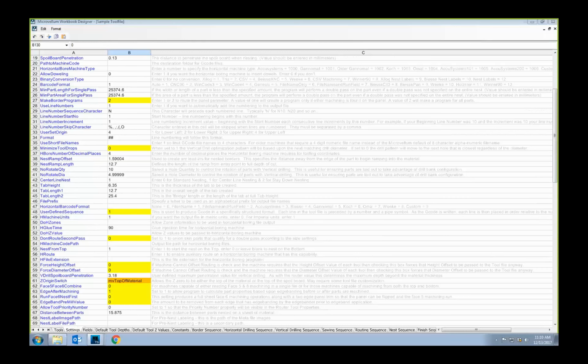All right, thanks, Shane. Yeah, so this is definitely a great time-saving tool, especially for those who are running bottom edge machining. Without this tool, as many of you know, we provide a separate G-code file for that Phase 6, or maybe we can even merge them together, but there's usually a separate Phase 6 file that's generated. You would have to basically run it per part and then re-index it back. What this tool does is take that process away, allowing you to have one file for all of the Phase 6 and then flipping it back and making these trim cuts as Shane is talking about. So definitely a great time-saving tool.